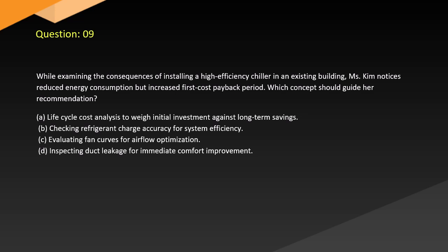Question 9. While examining the consequences of installing a high-efficiency chiller in an existing building, Kim notices reduced energy consumption but increased first cost payback period. Which concept should guide her recommendation? A. Life cycle cost analysis to weigh initial investment against long-term savings. B. Checking refrigerant charge accuracy for system efficiency. C. Evaluating fan curves for airflow optimization. D. Inspecting duct leakage for immediate comfort improvement.